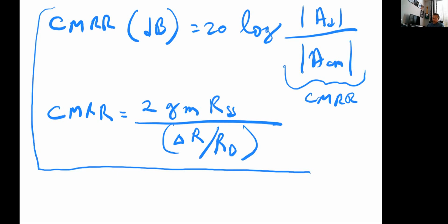Throughout everything that we've been talking about, another assumption that we have been making, which is not unreasonable, because we can match the transistors fairly close with a very tight window of control, is that they match. But they're not exact, and we want to know what the impact of that is. So another impact that is important.